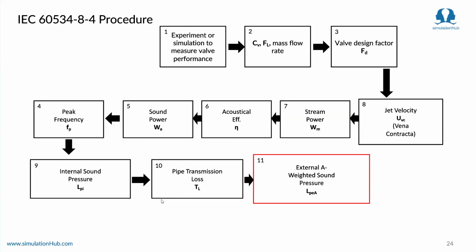This is the basic flow chart, or just the major steps that you go through to calculate the hydrodynamic noise using IEC equations. As you can see, as we move from getting the flow rate, which could be easily measured, even the design factor, FD, it's in the hands of the valve manufacturer.